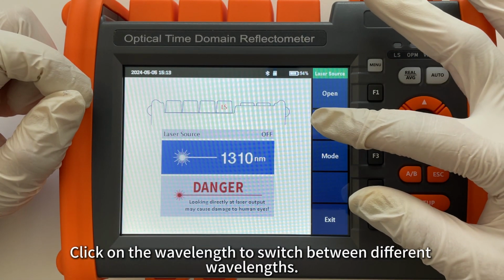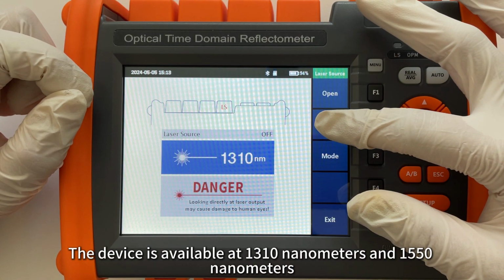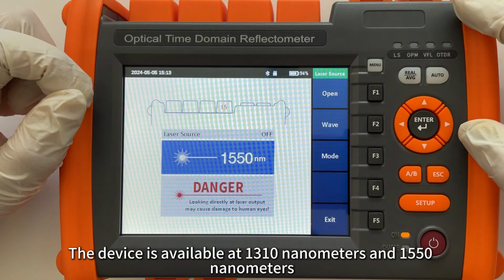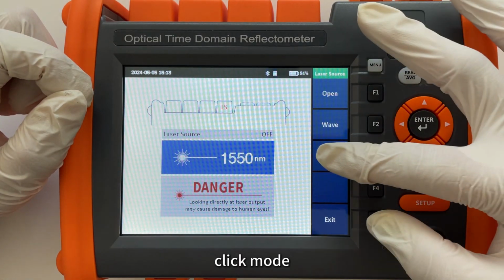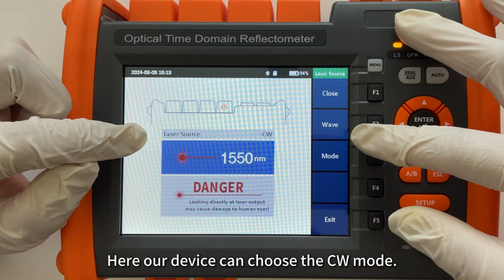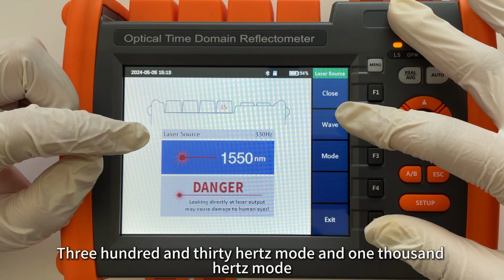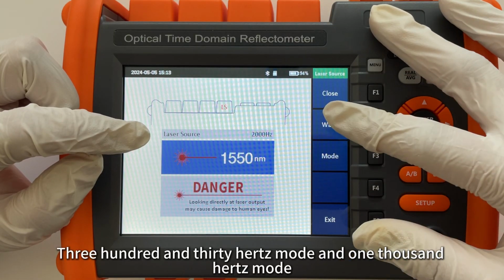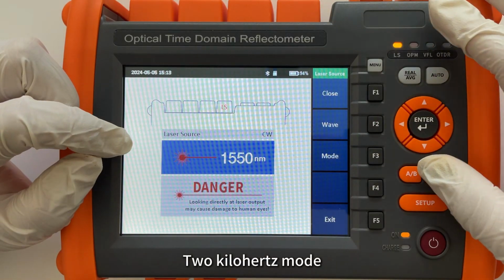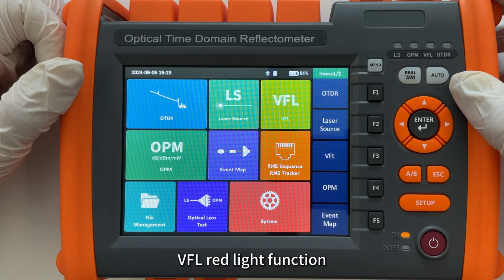Click on the wavelength to switch between different wavelengths. The device is available at 1310 nanometers and 1550 nanometers. Click Mode to switch between different frequencies. Here our device can choose the CW mode, 270 Hz mode, 330 Hz mode, 1000 Hz mode and 2 kHz mode.